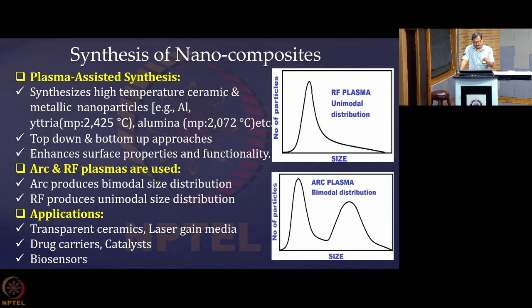When the nucleation stops at a certain temperature, that is the final diameter or size of the particle. They are nucleating, colliding with each other, joining together, and this joining stops at a certain temperature, below which you will not get any coagulation of the particles. Whatever size you achieve at that time is the final size.